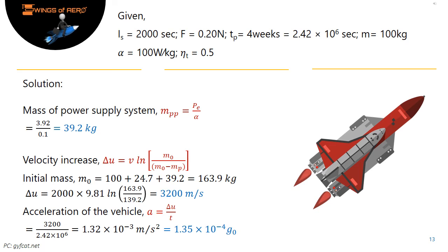The flight's energy increase after 4 weeks of continuous thrust producing operation is not enough to get from low Earth orbit to geostationary equatorial orbit, which would have required a change of vehicle velocity of about 4700 meter per second with continuous low thrust as compared to the 3200 meter per second above.